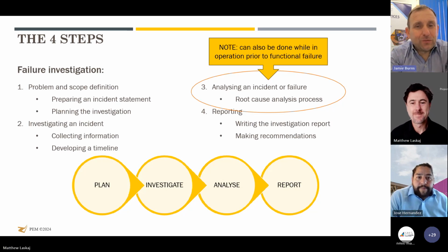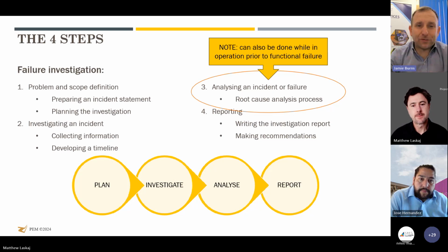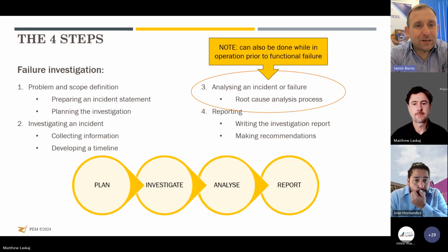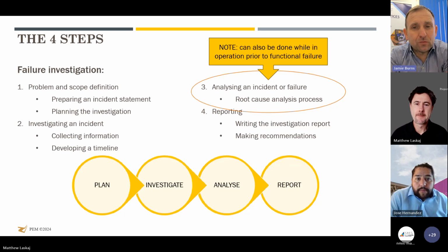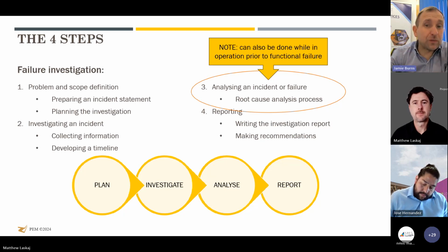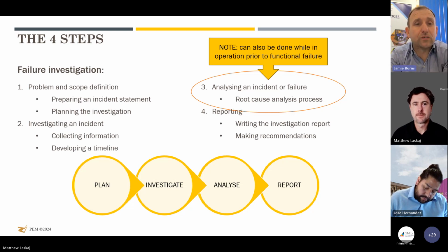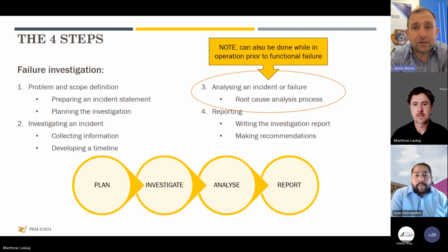Well, from years of experience of doing RCAs after something has failed, it's always more difficult because a lot of the time the failure is a consequence of something else. If we take a piece of rotating equipment, sometimes it's in so many different pieces that trying to put all those pieces back together to actually show the jigsaw as it was can be very difficult. So one of the things that we try and do now, and we're seeing some good success on it, is actually most failures occur over time. So if you can gather data in advance, then something may still fail, but at least you can go back through the data stream and understand where it came from and where it started. But after the failure has occurred, if you don't have access to that data, it can be a long, drawn out, sometimes painful process trying to understand where the actual root cause was. The consequences are easy to see, but how they started can sometimes be difficult.